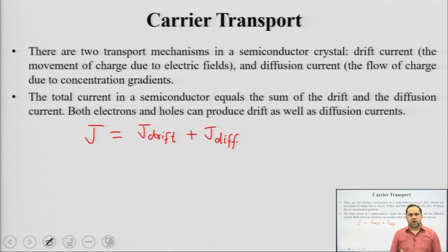Okay. Now, the requirement is the presence of an electric field. If you apply a voltage across a semiconductor of finite length, you are basically applying an electric field only. Electric field is voltage gradient, right. Even if you do not apply any external electric fields, fields can get induced or develop on their own inside a semiconductor, right, and those electric fields which are induced may also be able to produce drift of charge carriers.